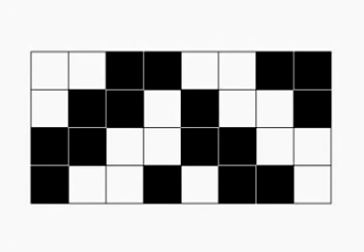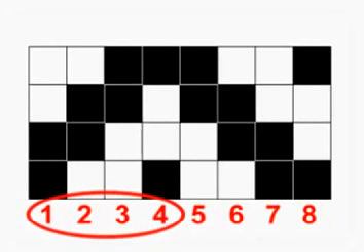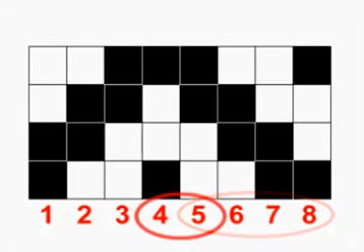Herringbone weaves are broken twill weaves composed of alternating left and right-hand twills to produce the herringbone pattern. This can be accomplished on a dobby loom using a straight draw, or by using a herringbone draw on a cam loom to produce the same effect. The chevron is a 2x2 twill that is right-hand on ends 1 through 4, and the weave reverses to a left-hand twill on ends 5 through 8. Notice that ends 4 and 5 form a point at the reversal.